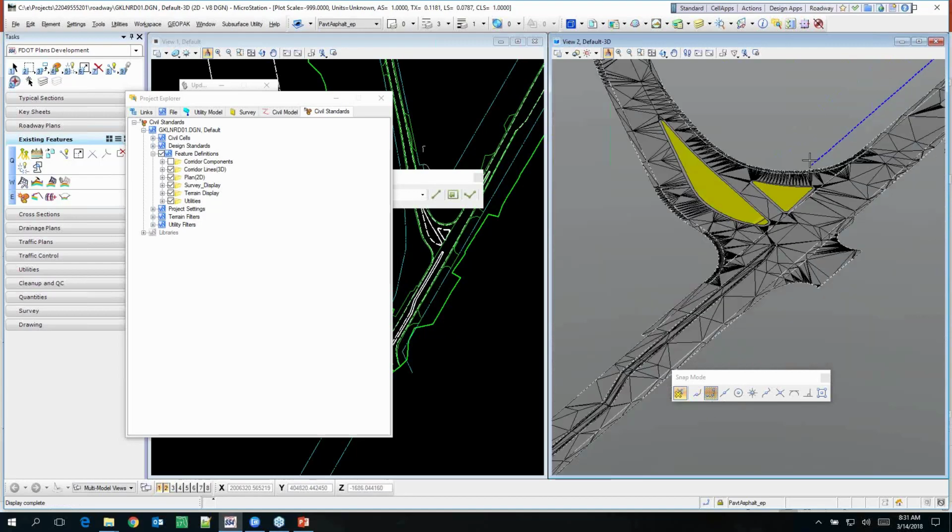Update that. So quick question, can you go over the difference between GKLN and GDTM again? Those are confused. GKLN, the idea is it's your lines file, and I think that's what the LN stands for, whereas the GDTM is just your surface file. Traditionally we've created the existing terrain in the GDTM file, and then we created a new file to build your existing features model.